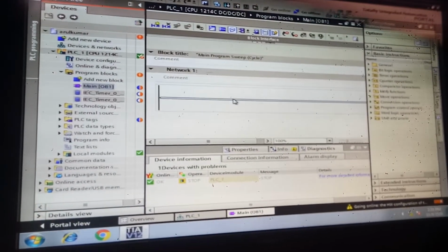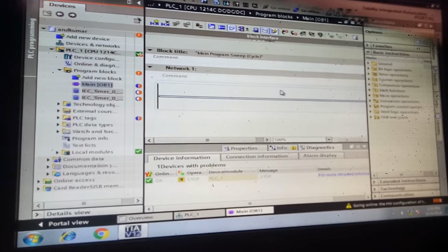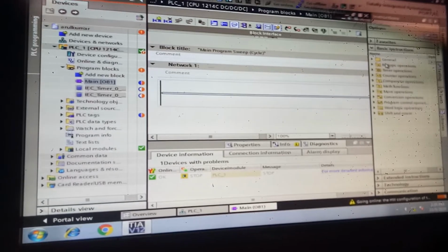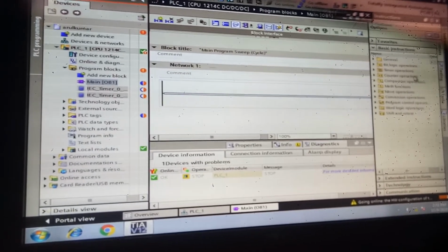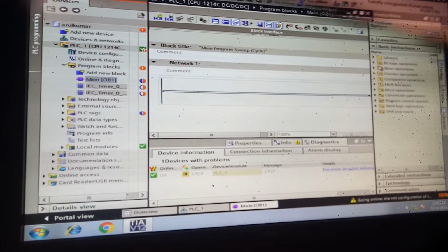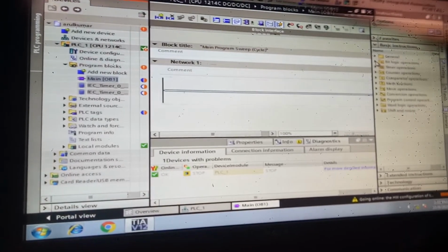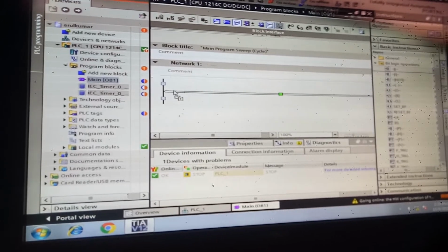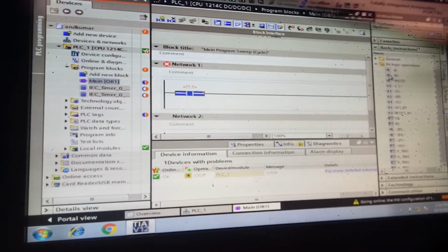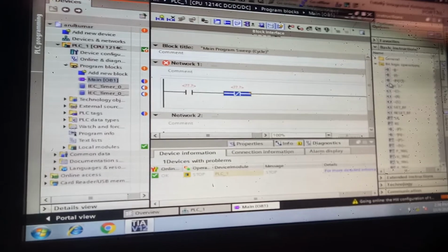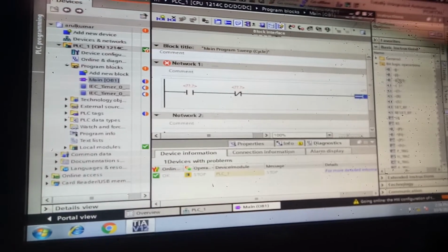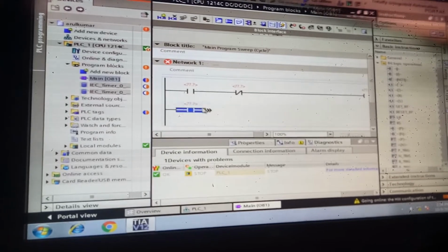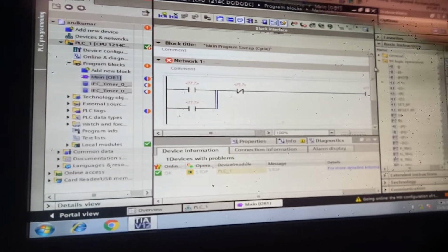So this ladder will come. Okay, so now you go for drawing the ladder diagram. Here we have the basic instructions, general bit logic instructions as well as timer operation and counter operation. So now you go for drawing the bit logic operations. In that, first I go for normally open contact, then normally closed, then output coil, then for latching, this can be connected here.